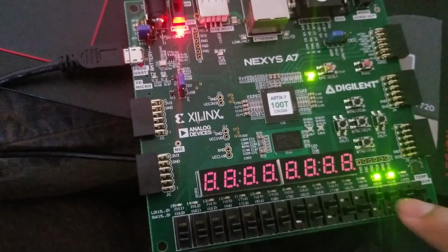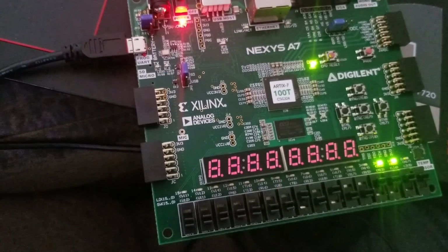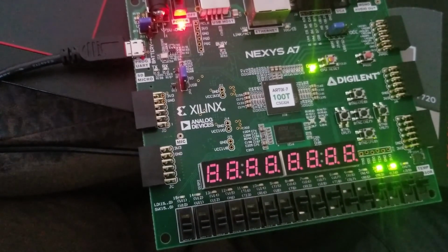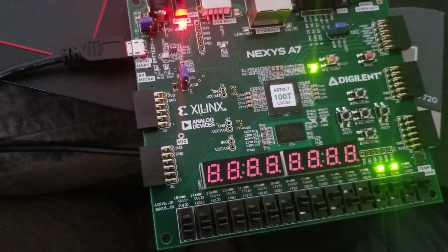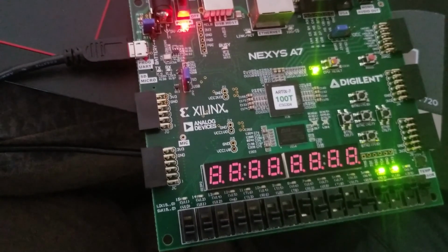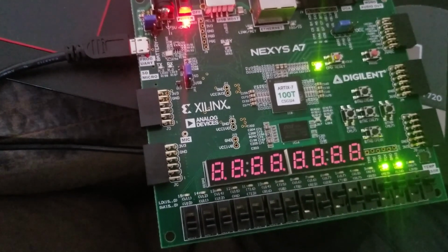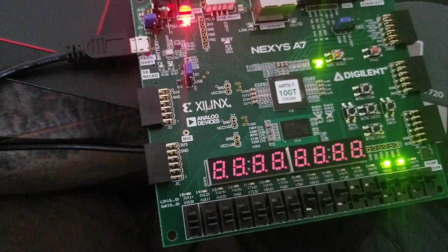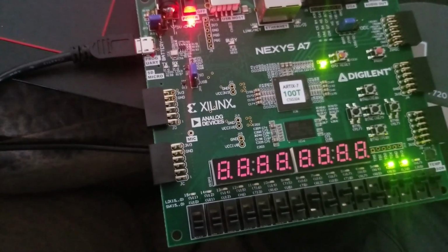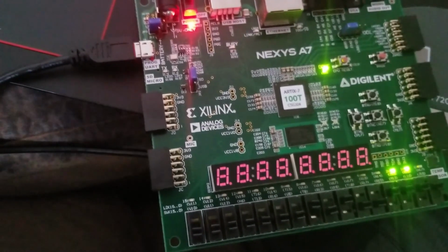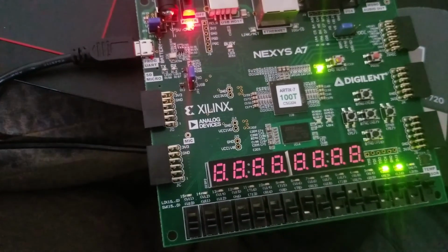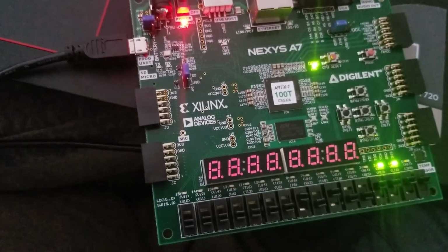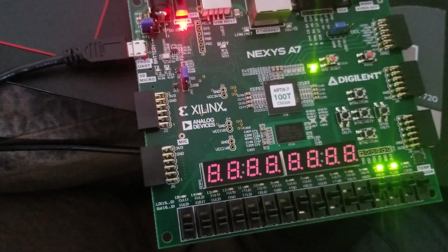Sorry, every time that I've been saying even parity in this video, I've actually been meaning odd parity. Even parity is when you're talking about not XOR. With XOR, you actually have odd parity. So every time you have an odd number of ones, you will have a 1 come out. That's what I actually meant. I'm so sorry for saying even throughout the video. So just as a point, XOR is odd parity and XNOR is even parity.